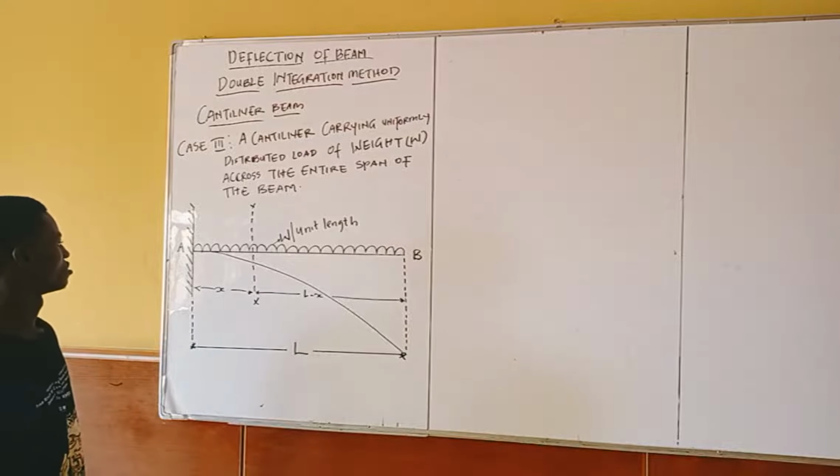So now, in this case, I want to give my upward force negative and my downward force positive. So now I have a force here that is coming downward. When I convert this one to a point load, W is positive, because my force is coming downward. I've already given it positive. And the distance covered when it was coming to this section is L minus x over 2.